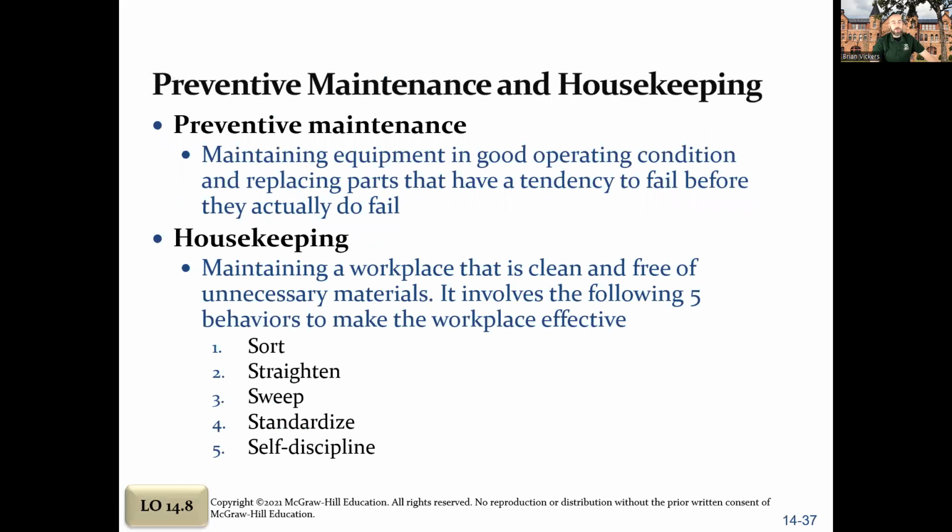Preventative maintenance. So continuously maintaining equipment on a schedule so that you're replacing parts that often fail before they fail, because if they fail in the production process, that can create a huge problem. So if you've got a belt that's worn out, or gears that become loose sometimes, or things that need to be oiled or they'll overheat, you're doing that before they fail, right? This is like getting an oil change before your engine locks up.